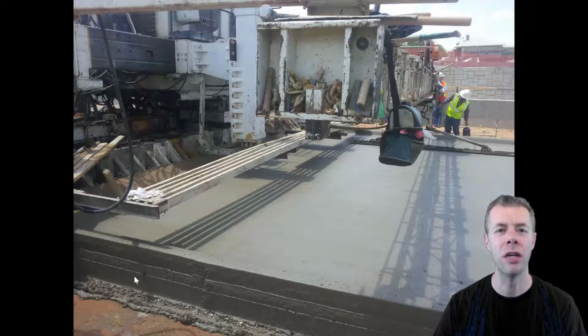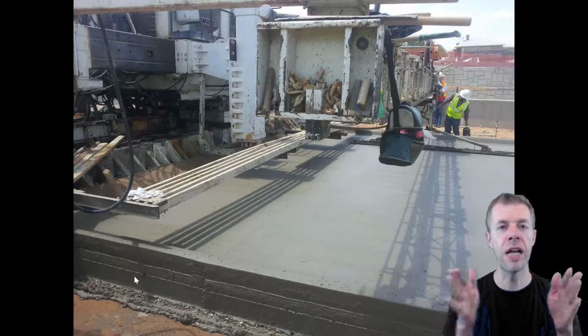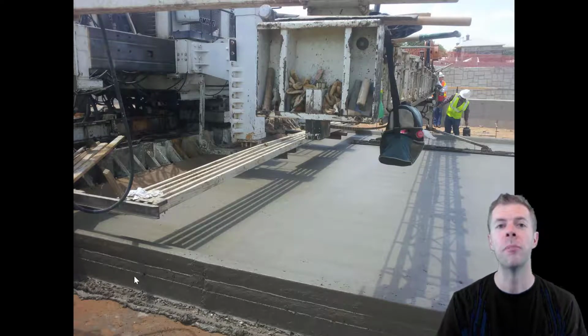It extrudes it. But to get this to work, you need concrete with a window of workability. You need concrete that's workable enough so that it'll respond to a vibrator, but not so super flowable that it doesn't hold an edge. That would be horrible, right? If it fell over, you'd have to put side forms on it, edge forms, and that happens sometimes. But you'd like to minimize that. And this window of workability is really important.